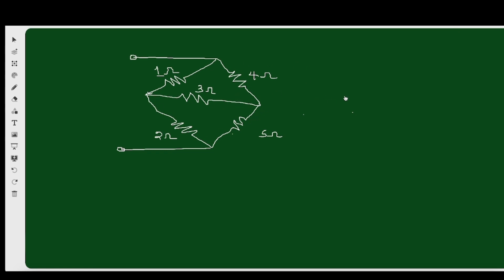What I will do is convert the top delta. So I will draw a resistor here, I want to convert it to star, and draw another resistor here. Let me call this R1, R2. You see that I won't be checking any formula before I can get this. I'll call this R3. So what will be my R1?